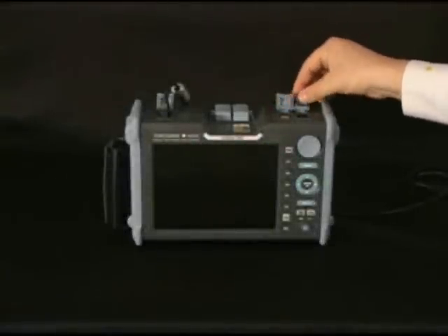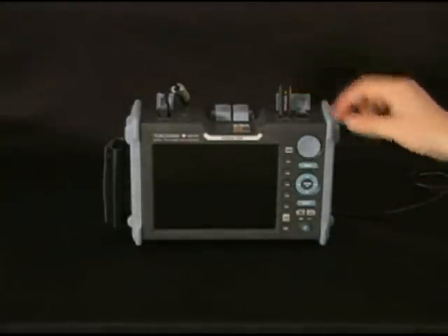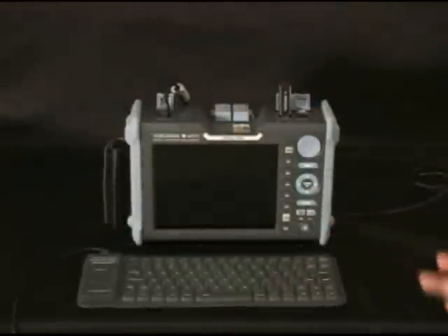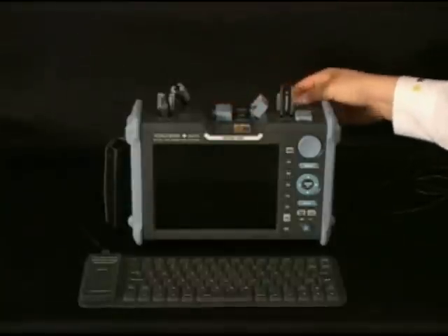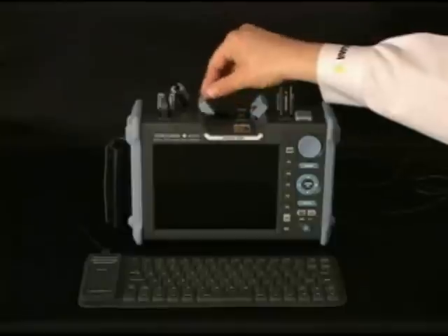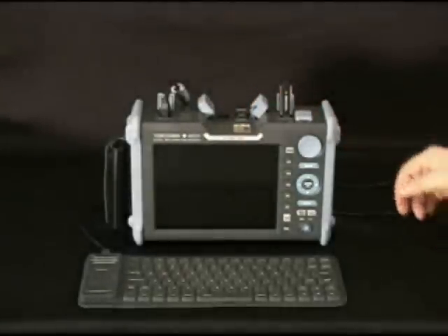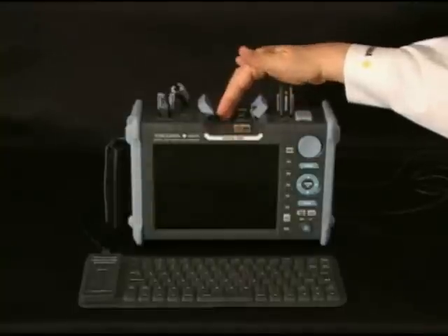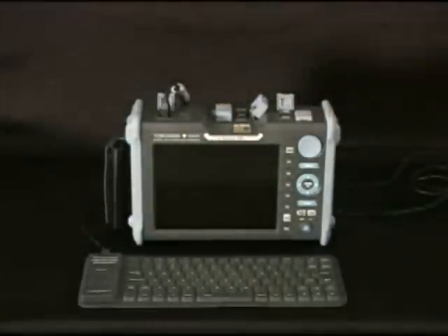Use the AC power adapter provided with the OTDR to convert from AC to DC. On the opposite side, you'll see dual USB ports. These ports will accept a memory stick, keyboard, printer, or provide remote access. In the center are the fiber measurement ports. Please observe the input limitations as specified on the label. If your OTDR only supports 1310 or 1550 nanometers, then the second measurement port will be blank.